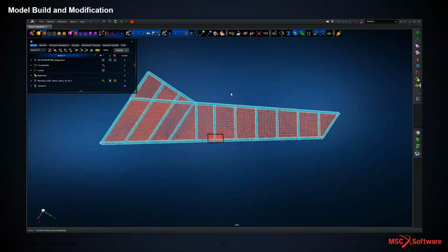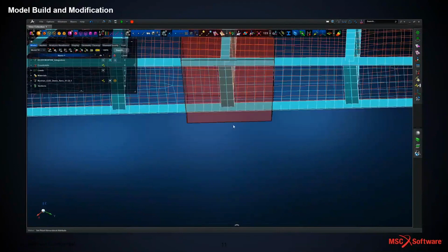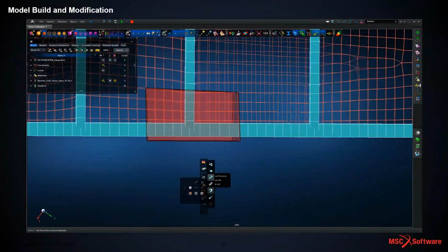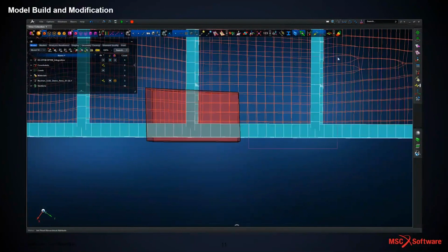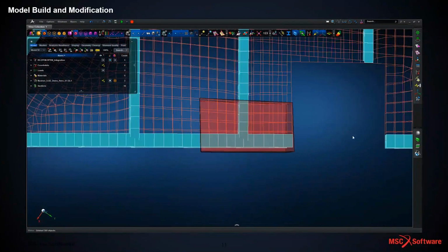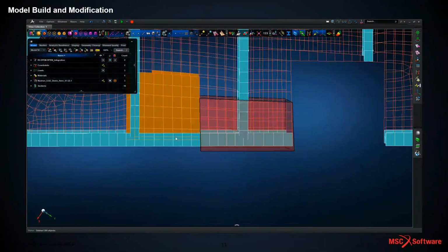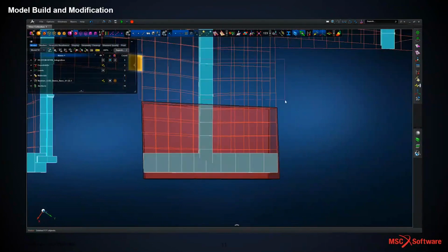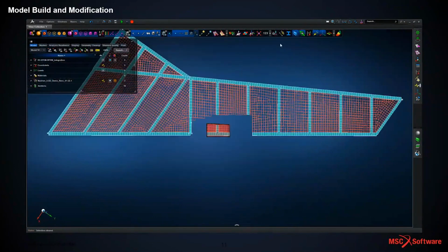So we've brought in a bulk data file. There's no associated geometry. We've simply created a volume, shown in the pink square here, to highlight the area of the model we wish to manipulate. So we're going to delete everything else from the database at this stage, and then redefine a local meshed region enclosed within that pink volume, just to give us some target definition for some of the orphan mesh workflow that we're interested in. So again, very powerful now.